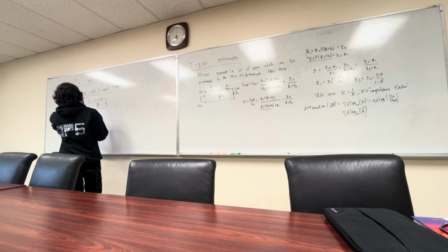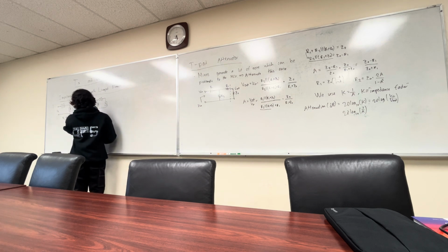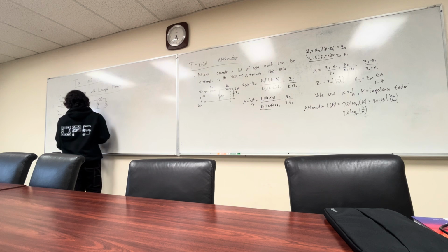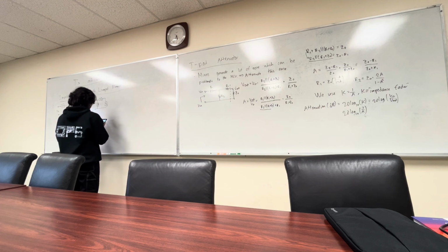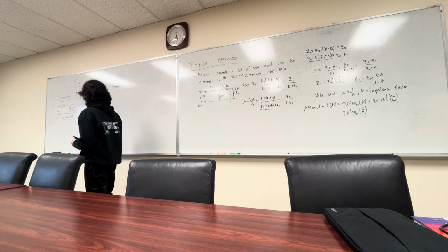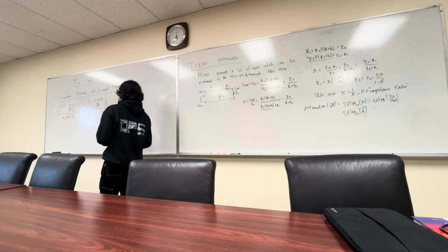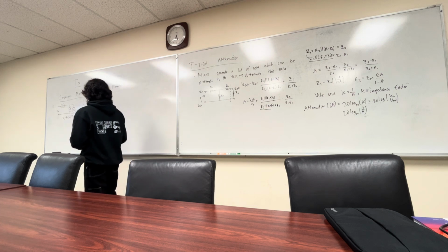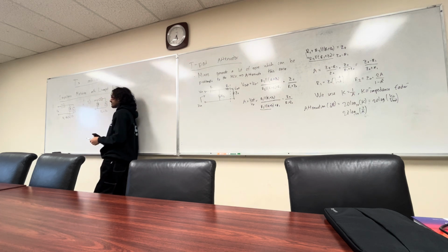Okay. So, first scenario, the real part of our load is going to be greater than the characteristic impedance, Z naught. The second scenario is that RL is less than Z naught. This is a bit weird to think about, because Z naught is like the square root of L over C, so it's not like there's a value and it's imaginary, but also not. But think of the number as all 50 ohms.